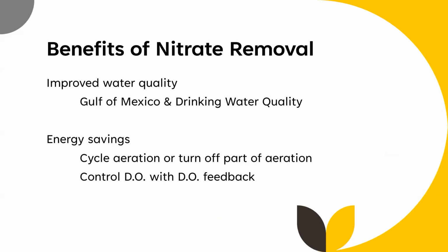So the benefits of nitrate removal are improved water quality, both for the Gulf of Mexico and for drinking water quality. And then you have improvements related to energy savings. And in the nitrogen webinar, we'll talk about air cycling. Many facilities, their very first step for nutrient optimization is to cycle air in their aerobic basin. Some facilities also turn off part of the aeration basin, but basically the amount of horsepower needed to supply air for your plant can be decreased, which can result in pretty significant energy savings at many wastewater treatment plants.